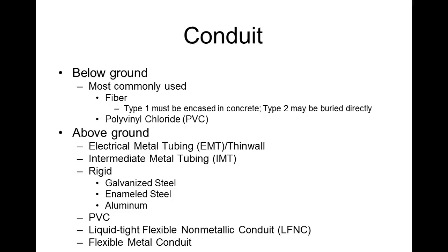These ceilings are too high, but if we look at these fluorescent bulbs right here, they would have conduit running through the ceiling, and then they have a box up there. We call them pull boxes or device boxes. But running down to the ceiling is flexible metal conduit. And of course, the metal is the jacket, right? What's the jacket in there for? Yeah, it protects against the environment. And of course, these things are constantly vibrating. The ceiling moves all the time, so we don't want to run any type of rigid conduit